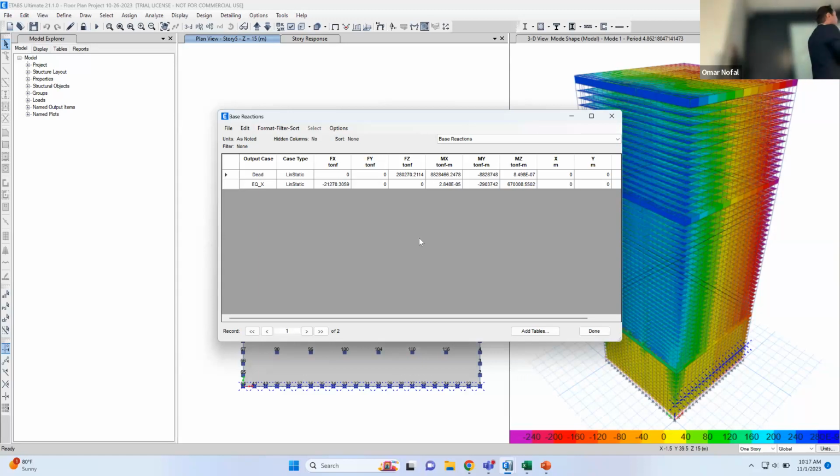And then you can actually draw the black curve. And once you have the black curve, if this one is the actual one, you subtract the maximum from this value, and this value is the delta, okay? So this is the value of the shear lag.